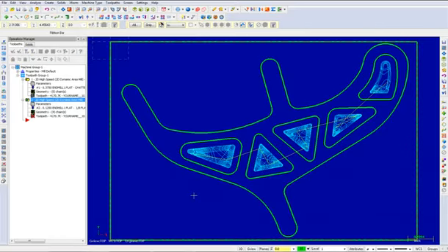Because the toolpath was copied, all the parameters were copied. Therefore, you do not have to change any other parameters. Now choose the Regenerate All Dirty Operations icon. We will now backplot and verify the operation to ensure that the tool motion is correct.